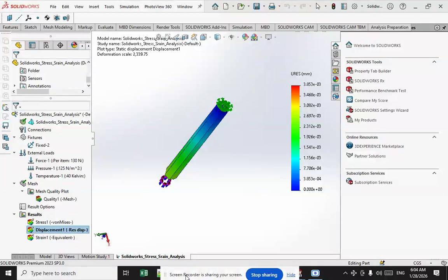The purpose of maintaining a factor of safety on yield strength is to prevent detrimental deformations that would impair the use of the structure. An aircraft with a permanently bent wing might not be able to move its control surfaces and hence is inoperable.